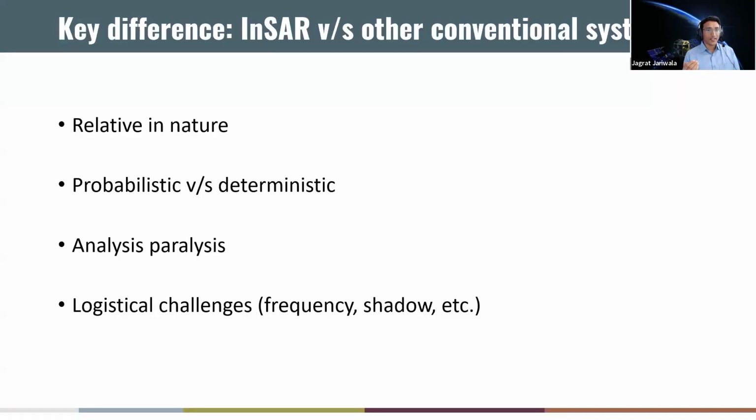If you have a case wherein, let's say, a vibration monitor gives you a threshold exceedance, and now you want to monitor your structure, you would not be able to get a surveyor on site and get it all monitored. It's not going to work in the same fashion with satellite imagery. It will come and look at the site whenever it gets above that area of interest.